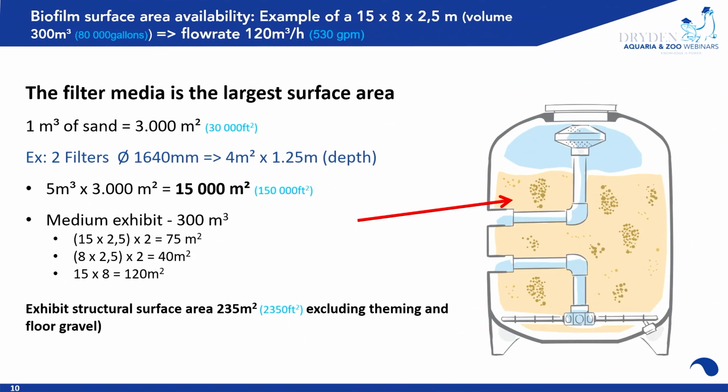Being able to capture as much dirt as possible without clumping, and then being able to release that dirt during the backwash process, and anything that's caught on that dirt. Sure, and release that dirt regularly enough before the organic material starts to putrefy, before it starts exerting an oxidation demand on the rest of your system, and before it starts adversely influencing your water quality. Now, these next slides just put some numbers to that.